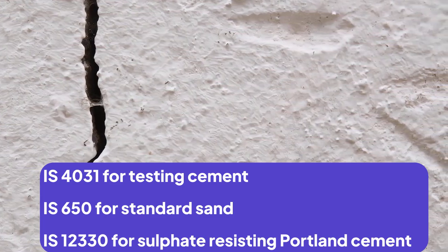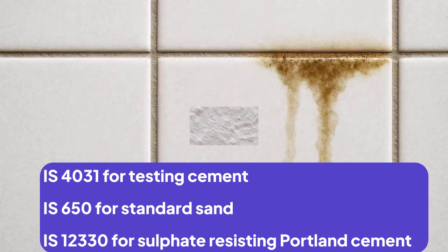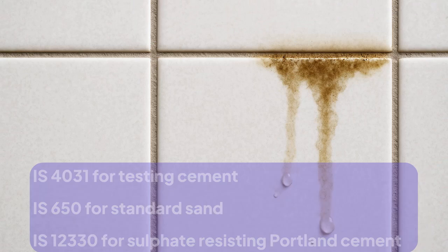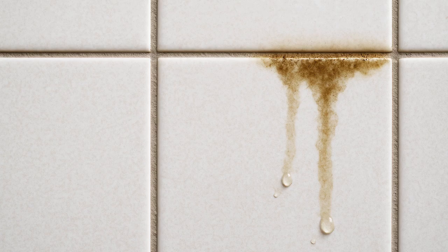They all need to follow whatever the code is for concrete, and that applies to cementitious grout as well. Now here is a catch. It's porous, can absorb moisture, and may crack over time, so it is not ideal for industrial or chemical-prone environments. Now see, these are the drawbacks of standard cementitious grout. But what is the solution?